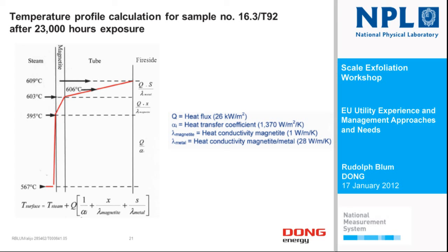So the total insulation effect, including the internal heat flux, will increase the metal temperature for oxidation, the mid-wall temperature, which could be used for calculating the creep rupture strength, and the surface temperature, which should be related to any eventual corrosion, fireside corrosion. And using such a test facility, you get the right figures, otherwise you don't.